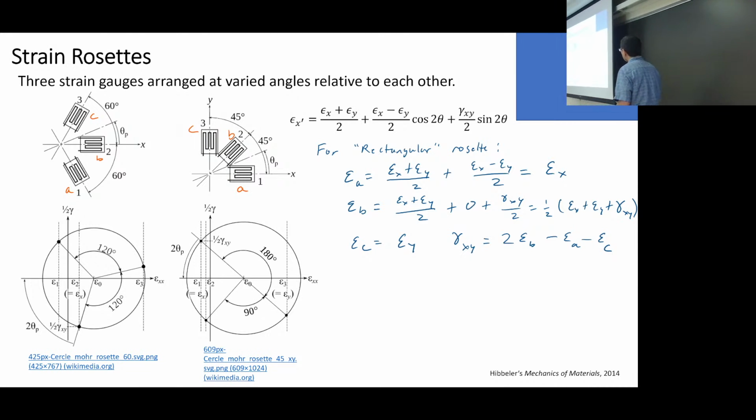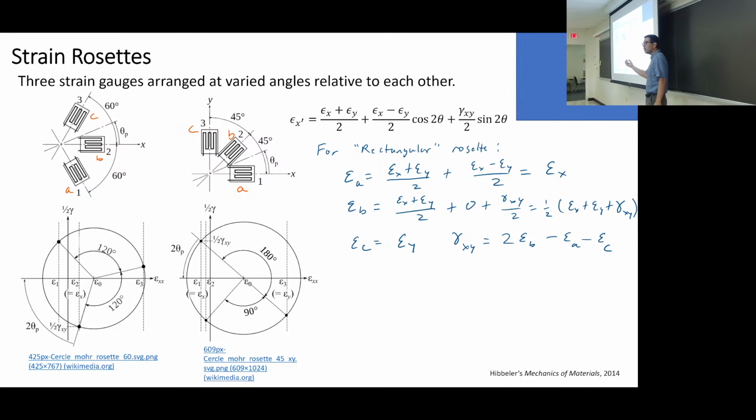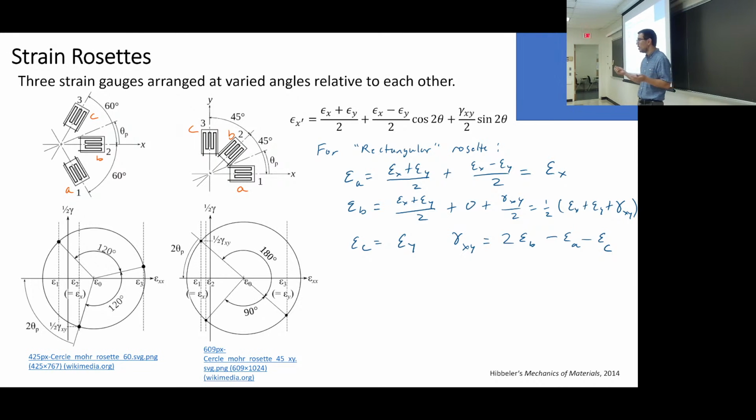Okay. These are useful tools. It's just some practical things. They're a pain to get right. And you're like, why don't I see products with strain gauges on them all the time? Well, one, they add weight, and they can be expensive. But two, if you ever play with strain gauges, you've got to use the right adhesive. You've got to make sure that you get it nicely coupled, that the strain gauge is not slipping relative to the top surface.